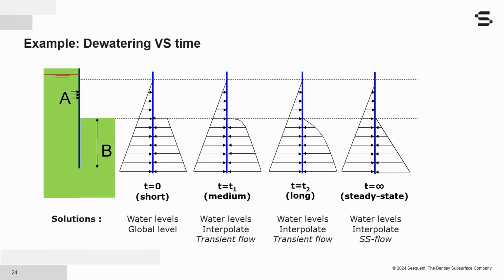So where does all this fit in? Now, we have some solutions here. If you look at the left solution, time t is 0, which would mean that it corresponds to a short-term situation. Basically, that is the undrained condition that we have defined. And then we have the other extreme. Let's look at the right solution, for which time t is infinite. Basically, it is the long-term solution, or rather the very long-term solution at t equal to infinity.